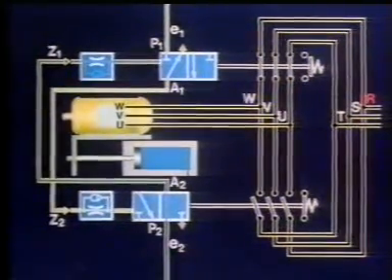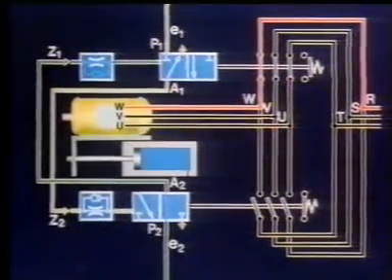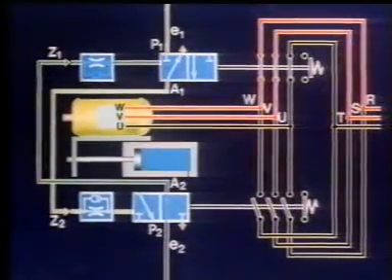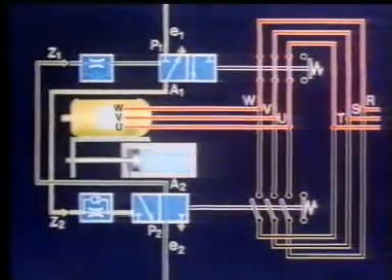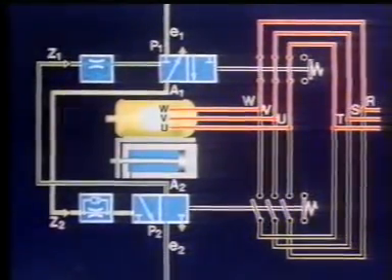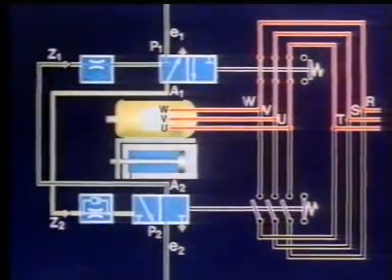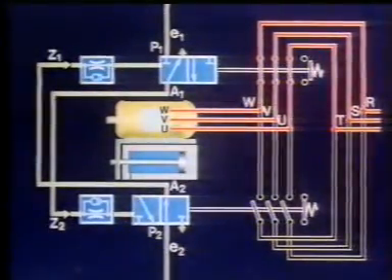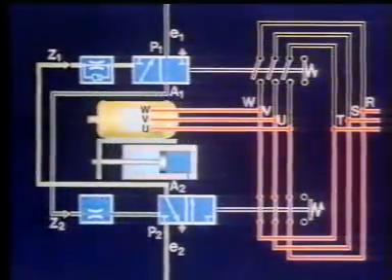The line R is connected to the motor connection W, S is connected to V, and T is connected to U. The motor now operates counterclockwise and the carriage returns. The contactor for counterclockwise operation blocks passage of signal E1. Simultaneous energizing of both contactors, and thus a short circuit, is prevented by this interlocking in the valve.